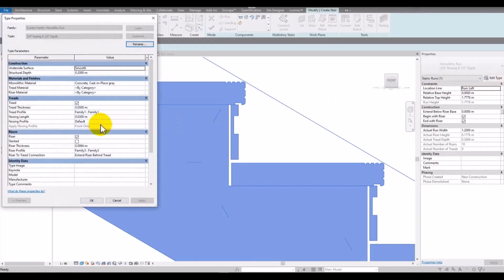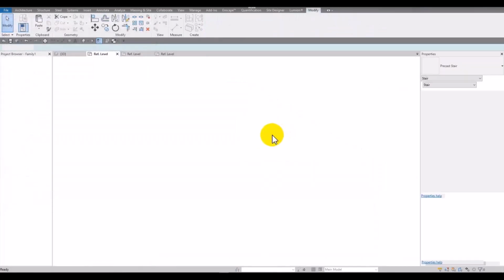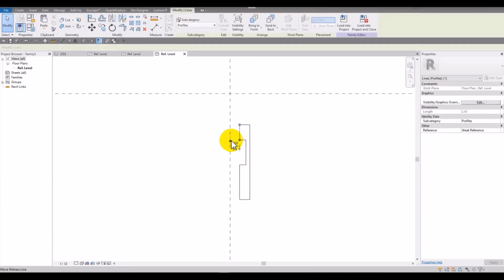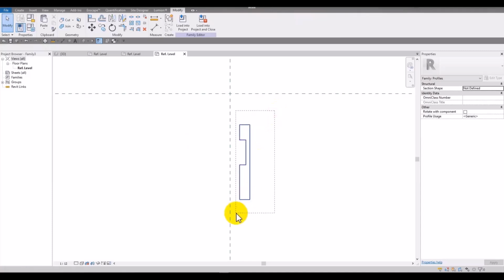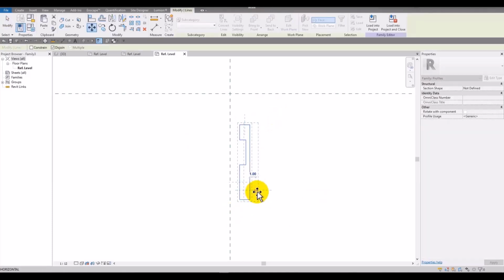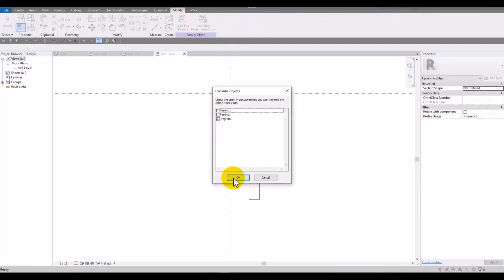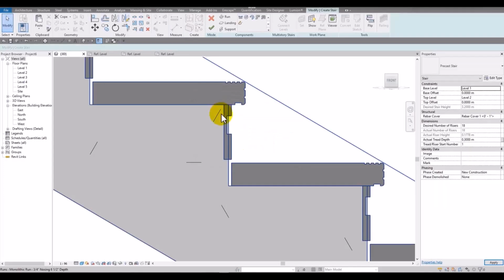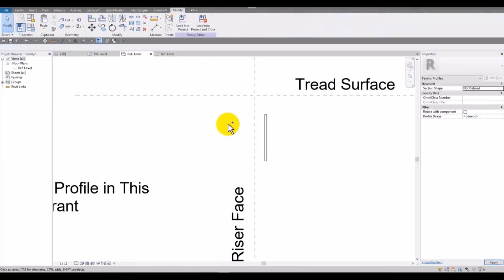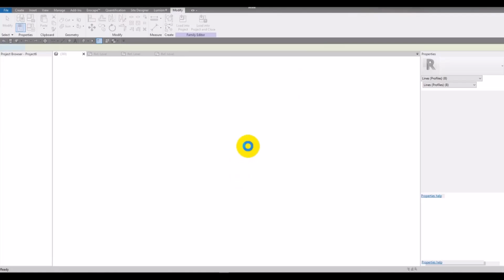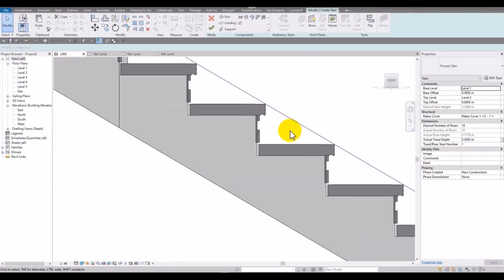Now it's here. It was 3 about the nosing, and here we can control it more. Now there is 1.5 centimeter distance. I can have 1.5 more, and it will be inside of the stairs because we don't have much space here, and we need to have the designs exactly the same as this space. I move it a little and it will be okay.